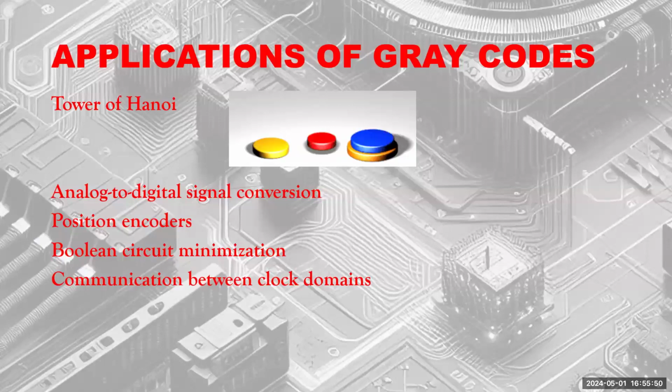Sometimes you may not discover the correct gray code branches. But mostly, if you can do gray coding so that most state transitions are covered through gray codes, you certainly improve the circuit. Okay, this is a VLSI engineer I'm talking.